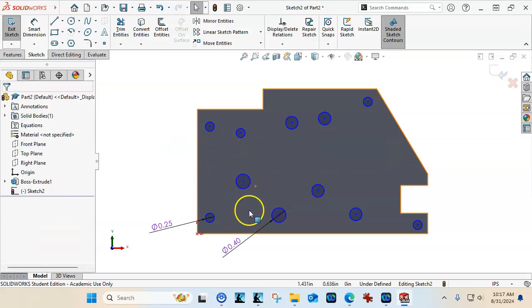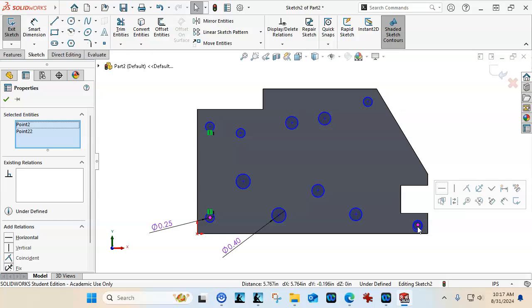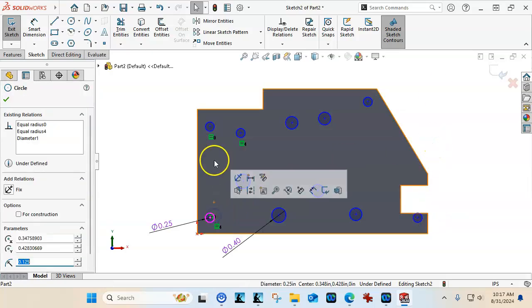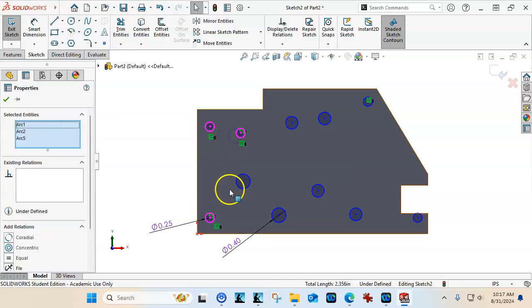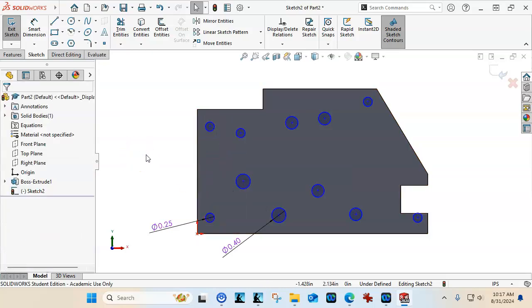So when I pick the multiples, I don't think I mentioned that, so I want to make sure it gets mentioned that when we select, hold down the control button and select, we go horizontal, or if we're picking the perimeters and whatnot, then we can set those to be equal. And as long as you're holding down the control button and keep selecting, you're going to keep adding to that group. All right, so we did B, there's only the C1.